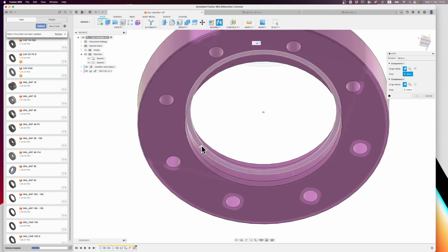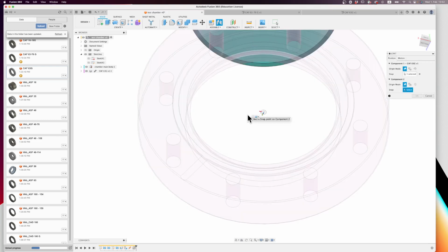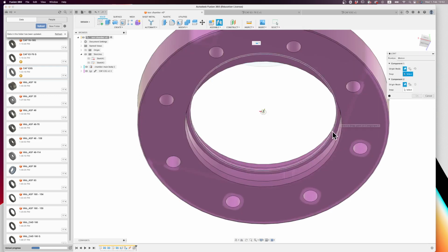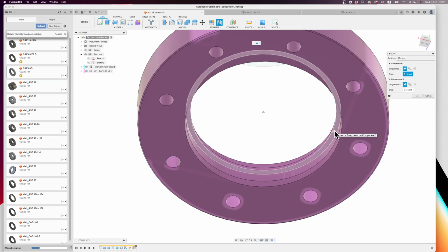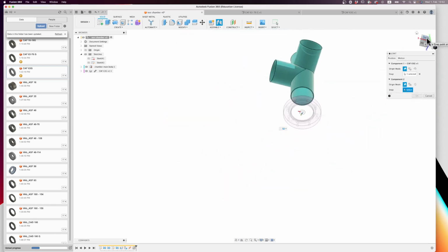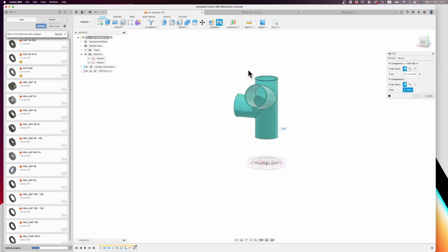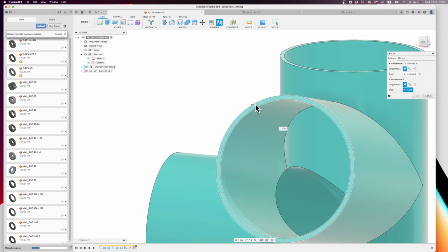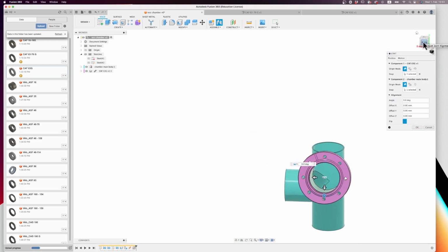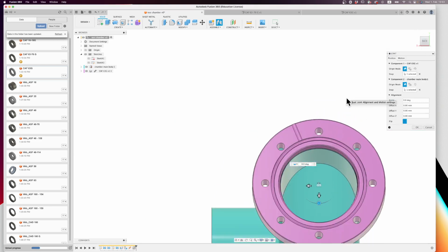And then we're going to take as a reference the center. This is where we would weld it on, the center of this ring. This is going to be our reference, and with the command button we can snap it to the important point. And then we're going to be able to snap it to the chamber, and we're going to put it onto one of the flanges here, so I can go onto the surface and then again move it to the middle, and off we go. And I put it onto the odd angled one, because this is a good example.